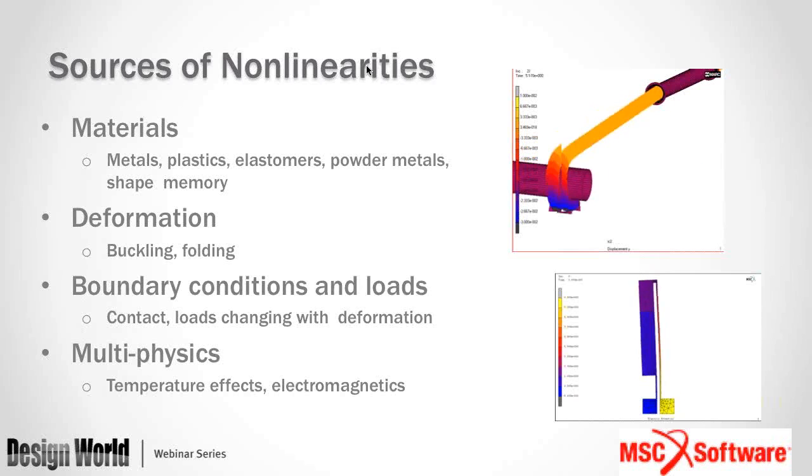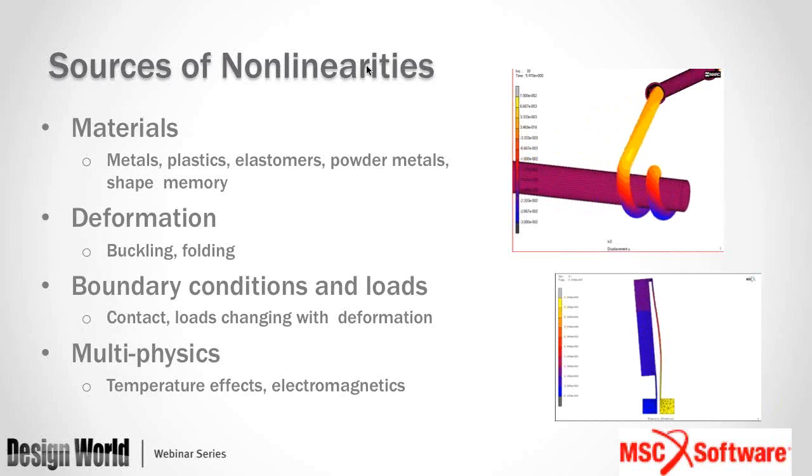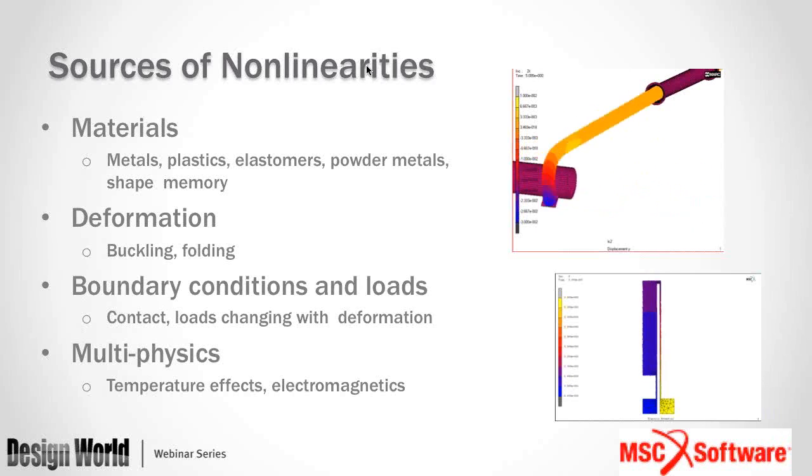With contact between various components, you may not know how each part would interact with the other parts, what the contact area is, how long it's going to last, how hard it's going to push, and so on. Also, one clear example is self-contact in rubbers, in other terms, the contact with itself because of some folding that is taking place.